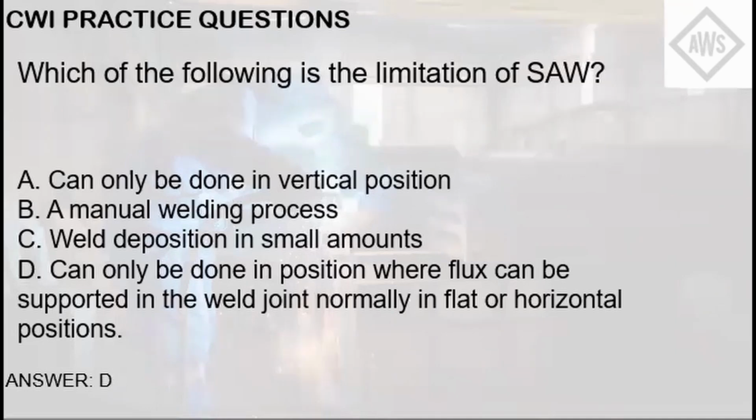So basically here, the limitation of SAW is that the machine must be configured in such a way that the flux will not fall to the ground, because if it is contaminated, you cannot use it. So it will just be wasted.